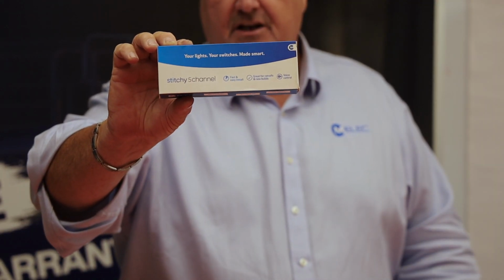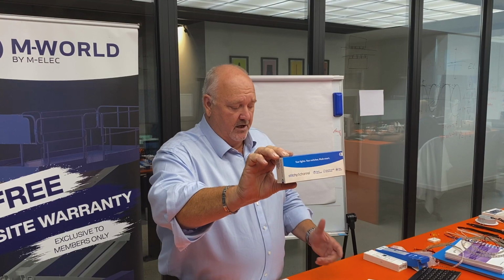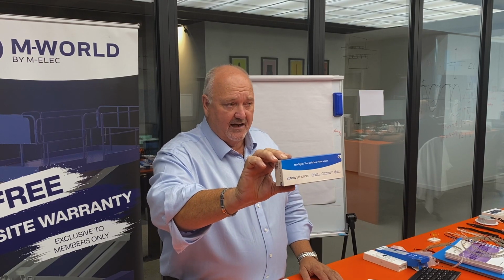In some instances, you can operate it through a computer. So we have our DALI, which will operate through a DALI system. They're all dimmers at the end of the day. They all allow you to control it, dim it, create a scene, a routine, or whatever you need. But without those, if it's just connected directly to a power supply, you've basically got on and off. If you've got a dimmable power supply, you've got your rotary dimmer on the wall, which you'd go back to in a conventional domestic dwelling.